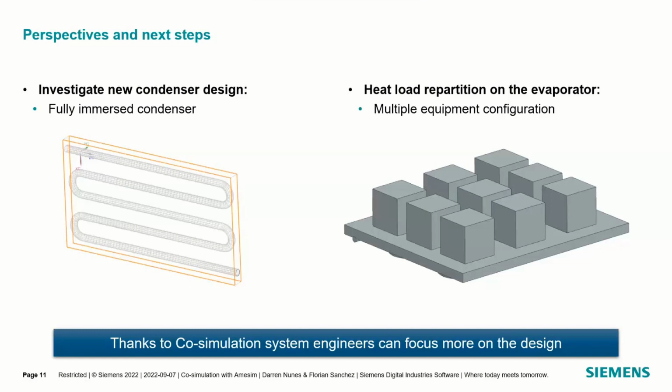Okay. So for example, for the model I presented, first I'm going to give some numbers about the computational time. The SimCenter MC model is really fast, on the order of magnitude of 1 minute, I would say. When we defined the co-simulation model, it took 30-ish minutes. It's basically due to the communication between the solvers, but mainly because of the 3D simulation.